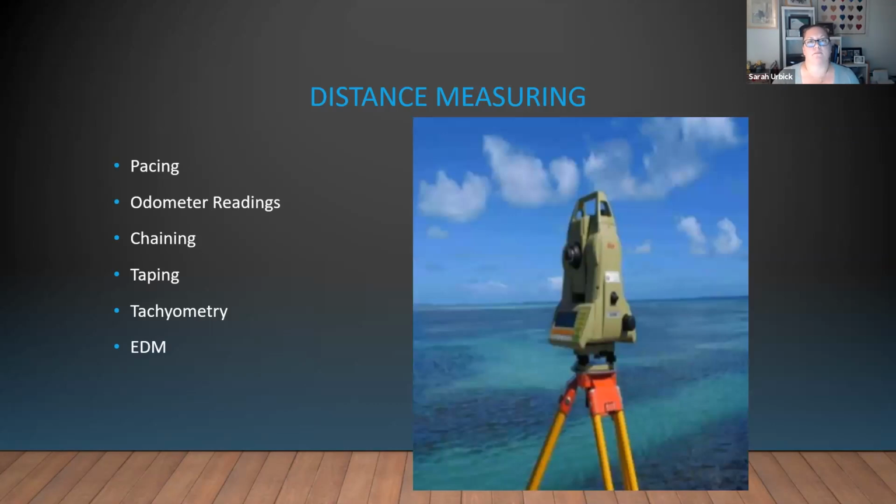Basically it's electronic measurements. Okay, total station. That's more what you're going to use. You're going to end up using a lot of these. Total stations can do not only distance, but they can calculate angles as well. They have internal calculators. You can reduce the size of a surveying party. If you're wandering around trying to maneuver these tapes and these chains and place pins, you're going to need quite a few people to do this.